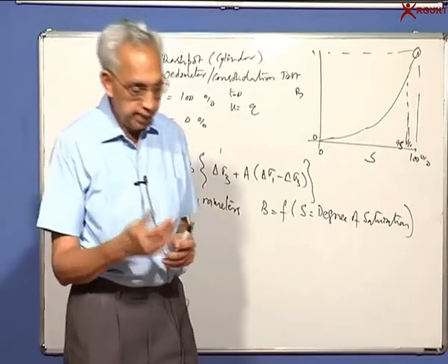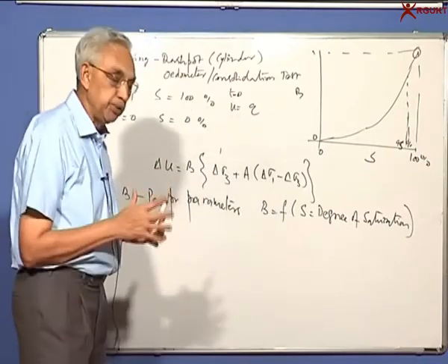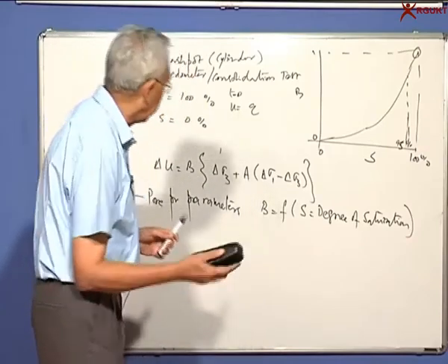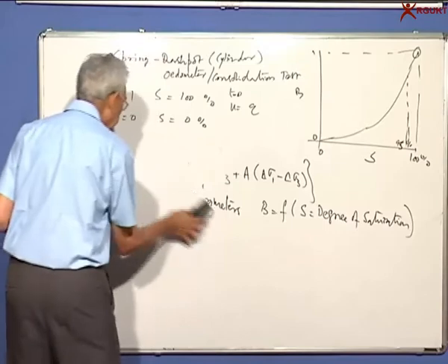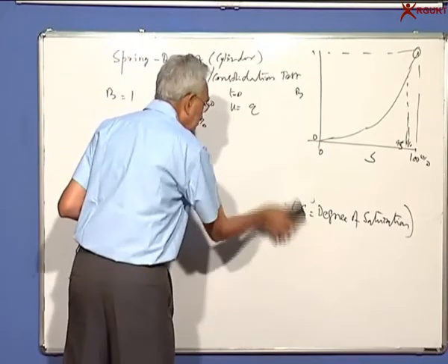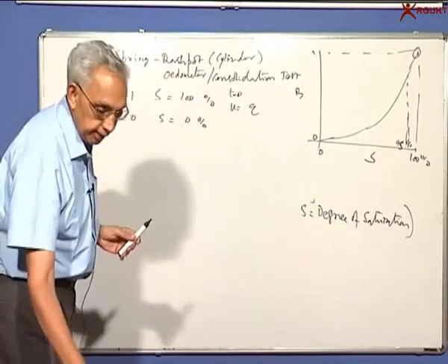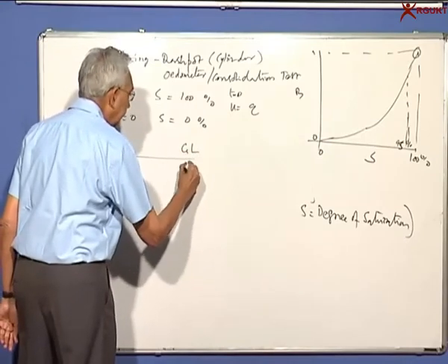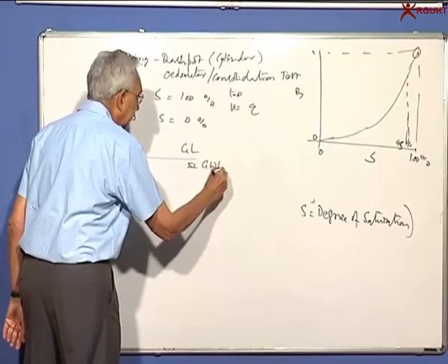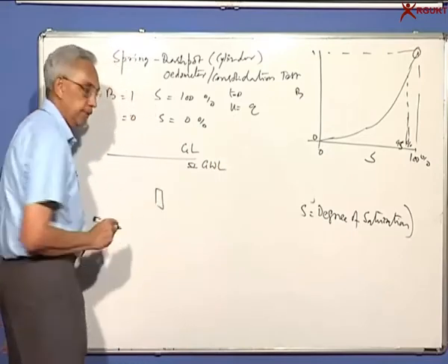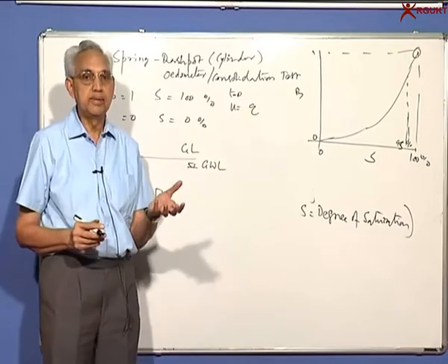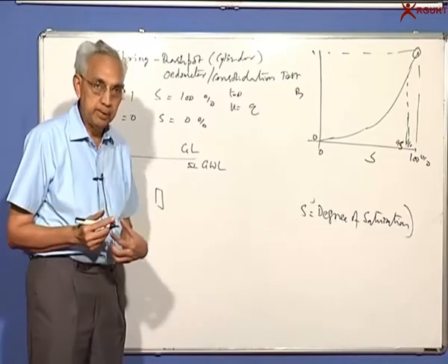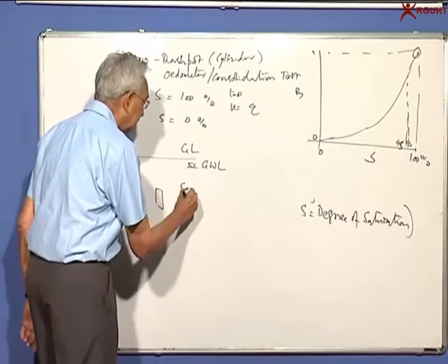So when we do the test, we try to make sure the soil is fully saturated, because at the site or in the ground, most of the time the groundwater table is high in case of soft soils. So if this is the ground level, and the groundwater level is here, suppose it is at 1 meter or 2 meters from ground level, most of the samples are below that, so the degree of saturation is 100%.